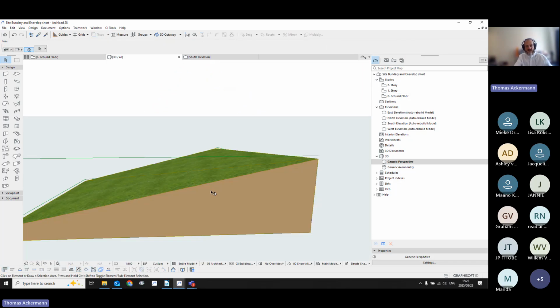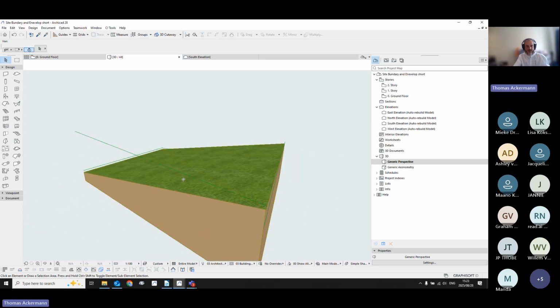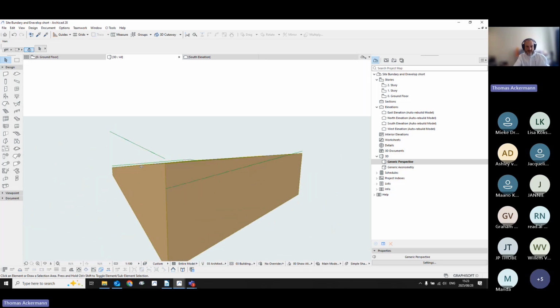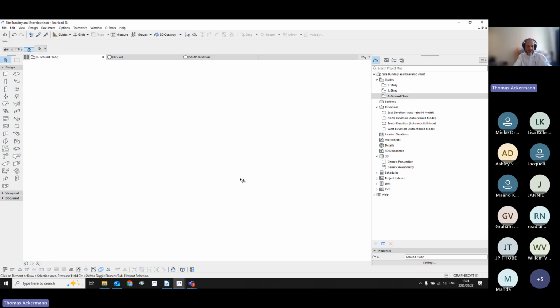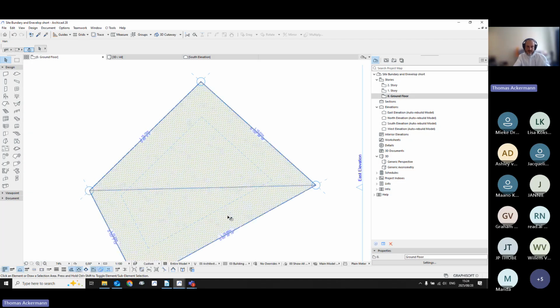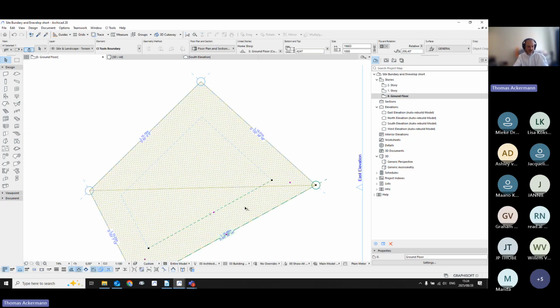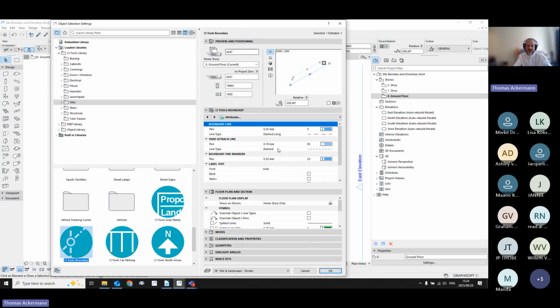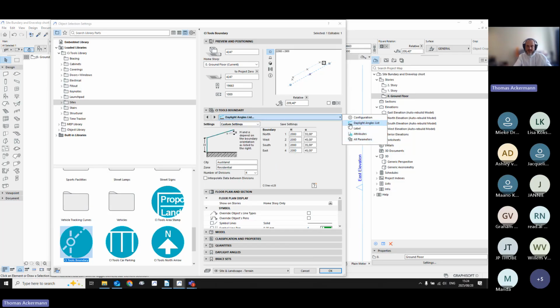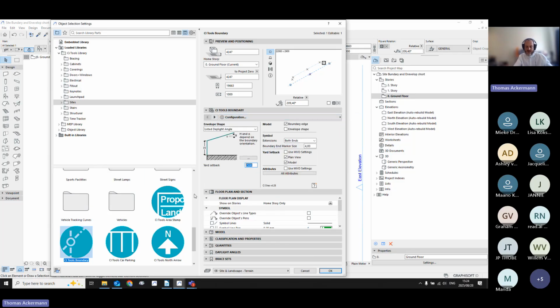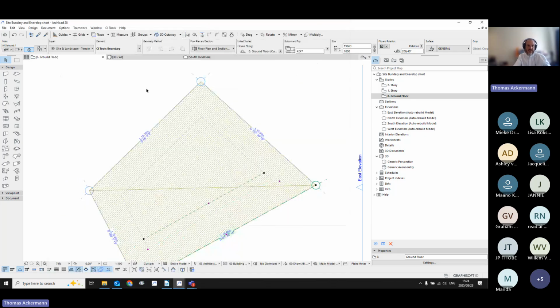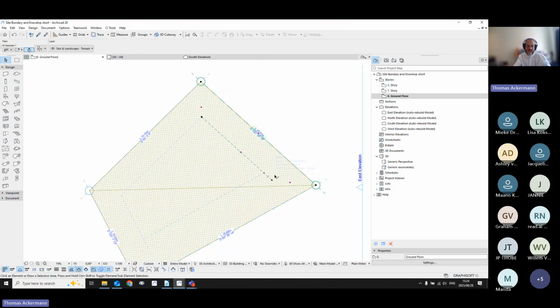They in fact have a 3D object that is also placed in 3D that you can hide, but there is an actual object that is now part of your project, and you can, at a click of a button, say, right, I want to actually change the distance on that particular side. We've got a 3.5 meter boundary. Click OK, and it automatically updates. You'll just have to manually move those lines, but it updates from there.